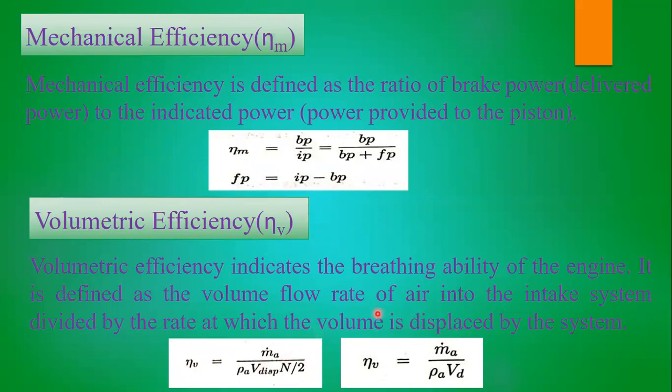Here, why he is specifically talking about air means, if it is a CI engine, we need to take only the air. Why? Because in a CI engine, only air is going to get into the combustion chamber. So keeping in mind these two engines, he specifically concentrated on air only. Okay, flow, he has taken the flow rate of air only. Of course, here air is in much greater quantity. Whatever the air is there, that is going to play a major role.